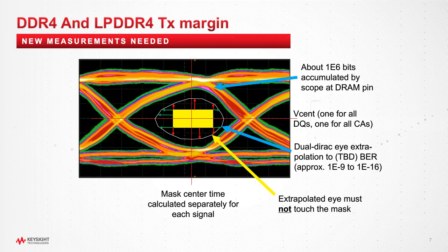So that point that used to be stable and reliable actually moves around a good deal, and it's the boundaries of where that sampling point can move that define what the data mask, the eye mask, looks like in DDR4.